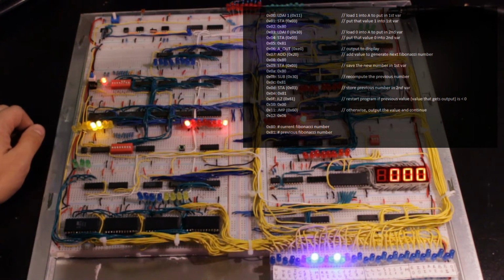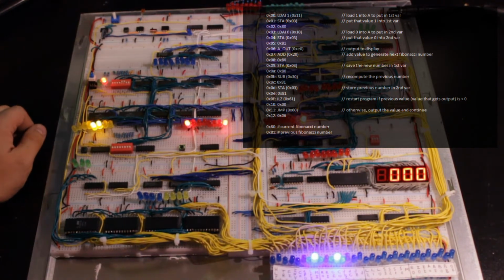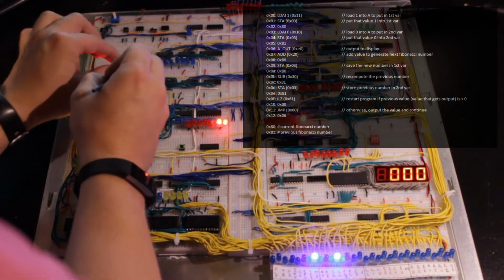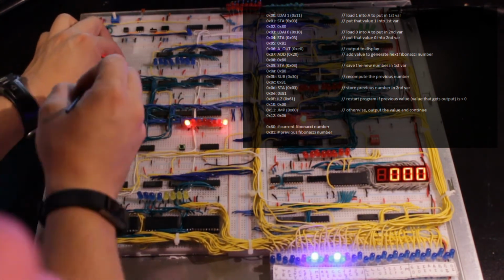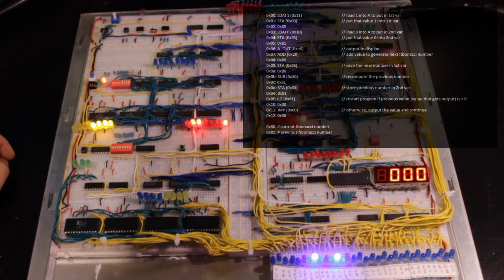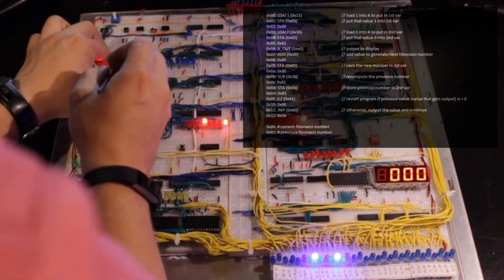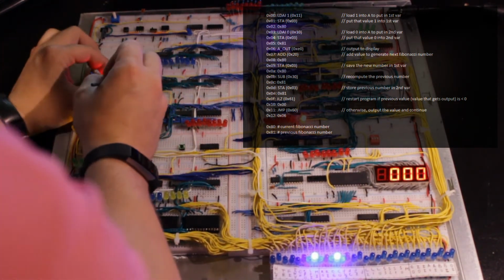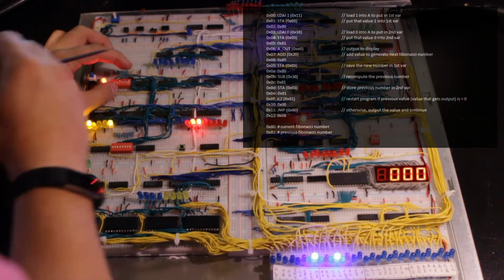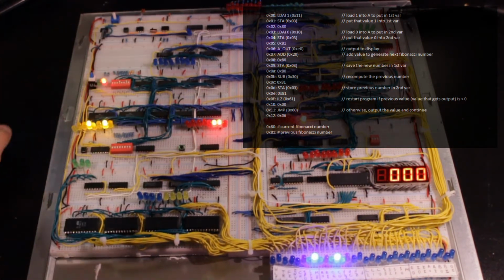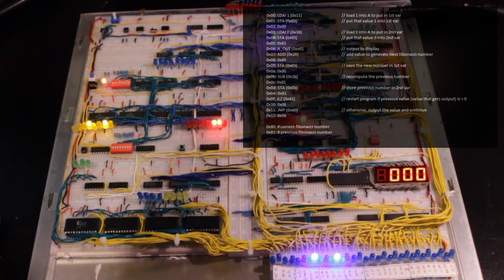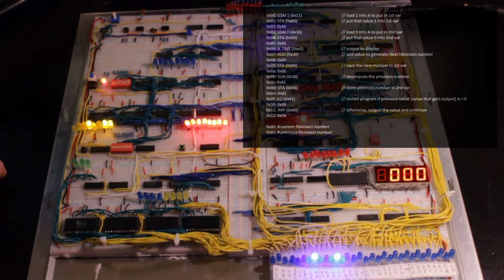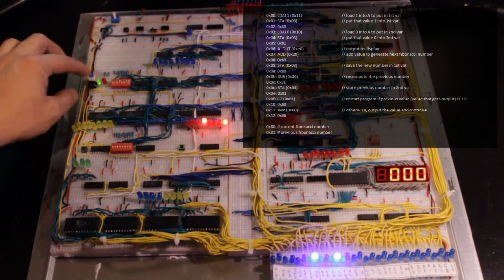Yes. Address 12, we want the pointer 0x81. Address 13, we want to store a command, 0x03. Address 14, the pointer, 0x81. Address 15, conditional jump less than 0, 0x61. Address 16, pointer to 0 location, so 0. Address 17, unconditional jump, 0x60. Address 18, the location of the output instruction, 0x06. And the next after that, halt, just for good measure in case the program goes awry.